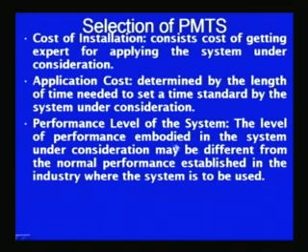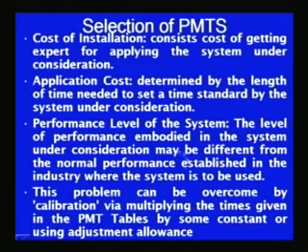The level of performance embodied in the system under consideration may be different from the normal performance established in the industry where the system is to be used, and to cope with the difference in performance of the job which is being done in a particular organization and the performance corresponding to which data has been developed in the PTS system, this problem can be overcome by calibration, by multiplying the times given in the PMT table by some constant factor or by using an adjustment allowance.